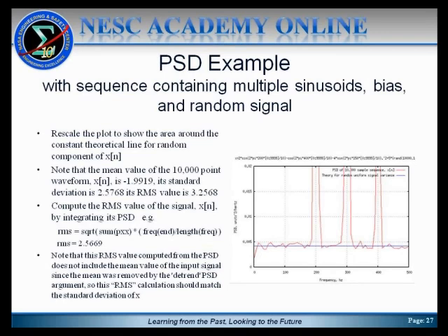you can calculate the mean value by just summing up the PSD values and multiplying them by the frequency per data point, if you will, and that's what the calculation shown here towards the bottom is, where I've just actually summed up PXX and multiplied it by the last frequency divided by the length of the frequency array, and that comes out to be an RMS value of 2.515.